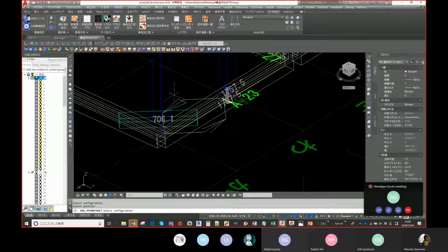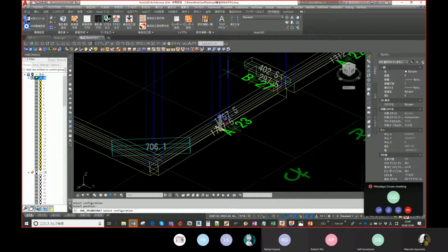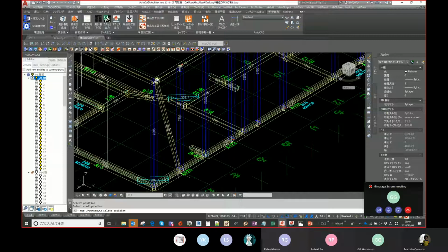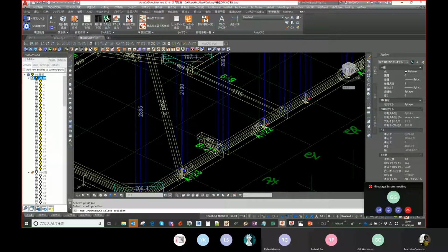So you can move with your jig to select. Here you only want to have one. If she goes closer to the middle, you will see there are two, and if she goes to the other side, you will see that the direction of the rising one will change. So you have in fact 4 options, which you can choose just by moving your mouse around and make that easy selection. And now this diagonal stud is inserted.